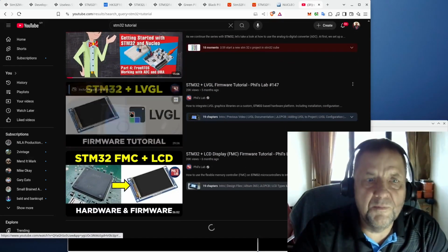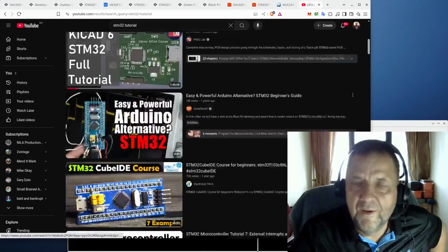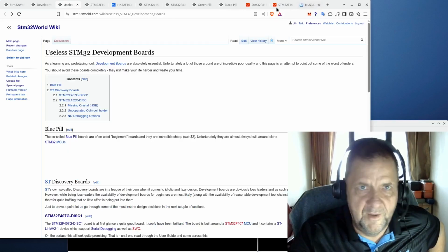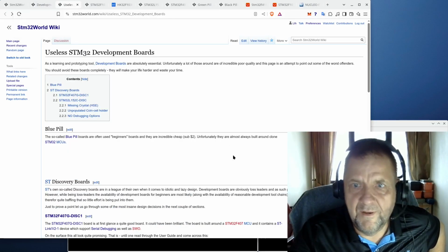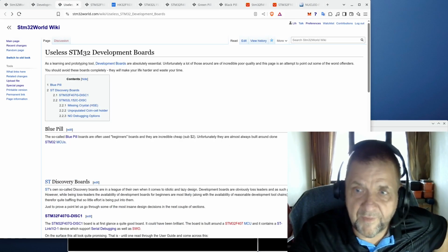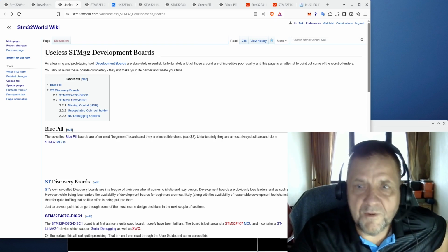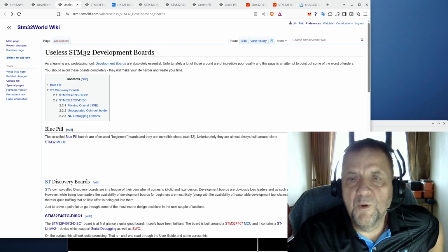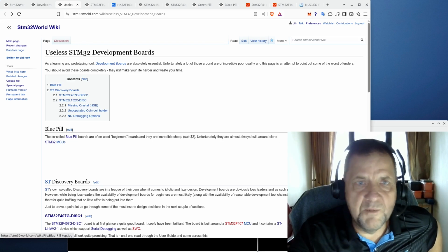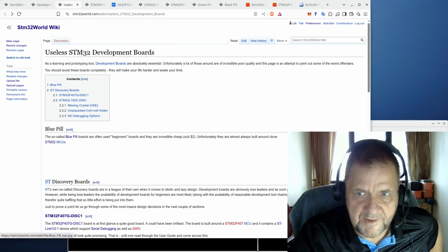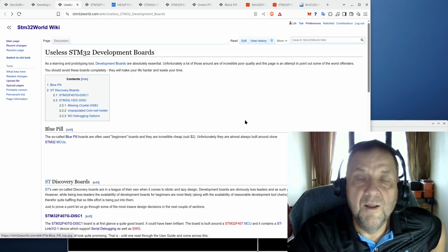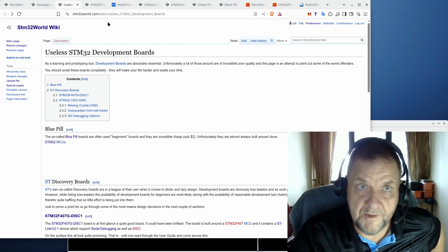Most of these videos will actually use a Blue Pill board, and in my opinion, it is completely and utterly useless. The main reason for that is that 90% of, if not more, I would say probably 100% of what you buy out of China of these boards does not contain an STM32 microcontroller. They will, however, pretend to contain one.